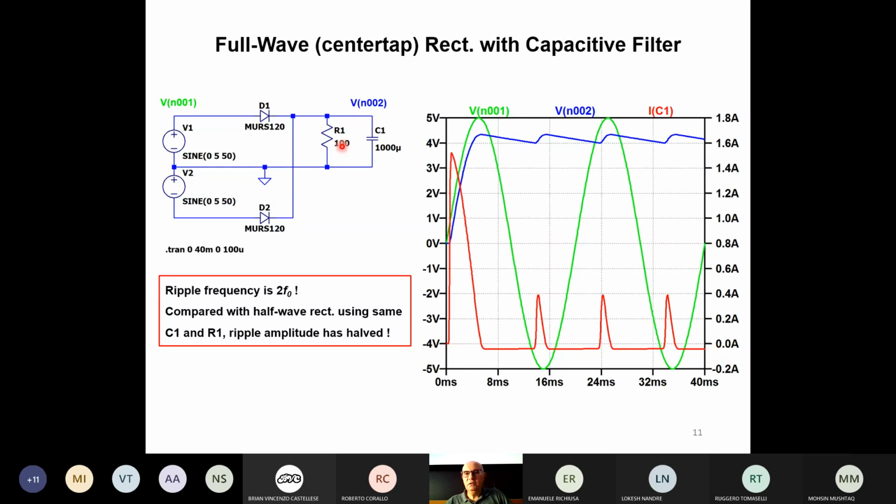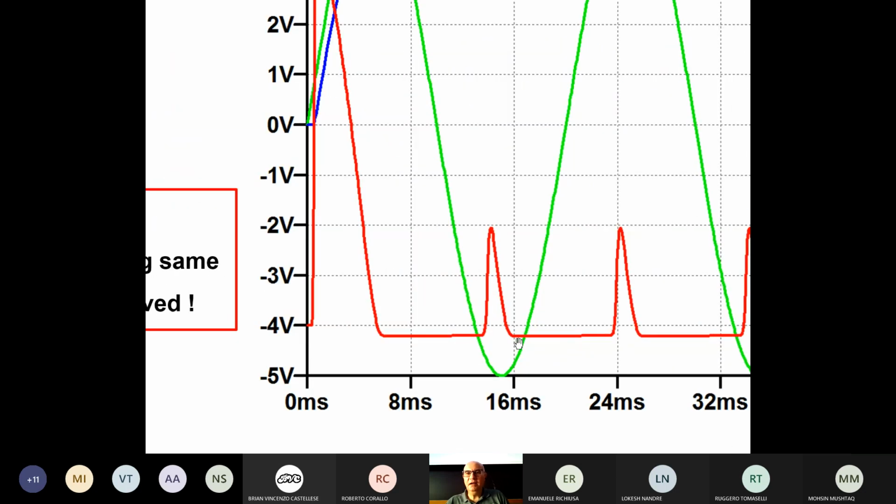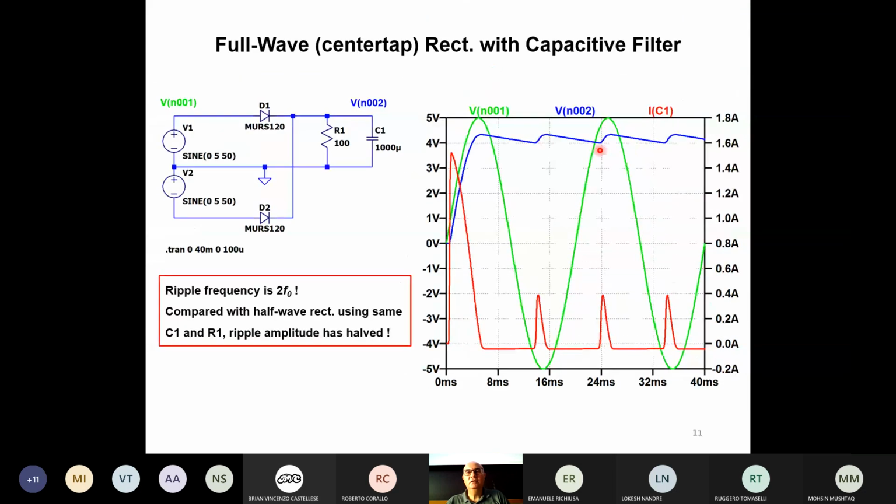What is interesting is that this current here can be considered almost constant, because the capacitor is large enough that the voltage variation is very small. That is a hypothesis that we are going to use in the next demonstration. But we can still see, if we zoom a lot, that the current is negative but decreasing a bit. It follows the voltage that is decreasing as well. But on average, this current is quite constant.